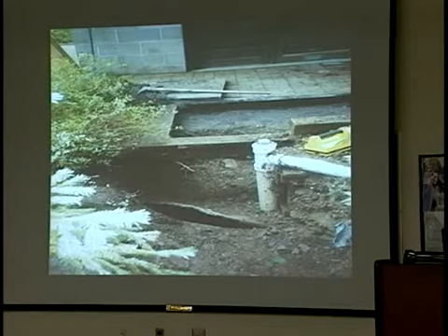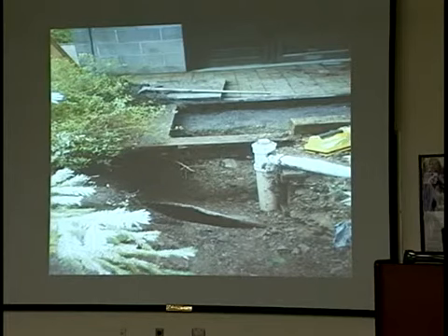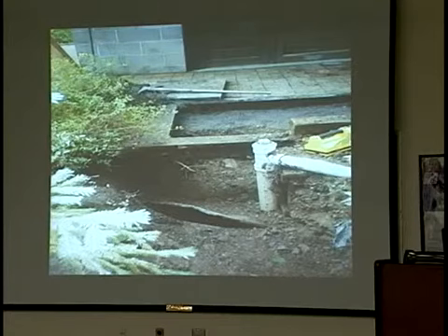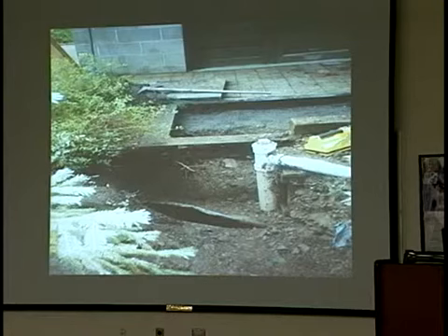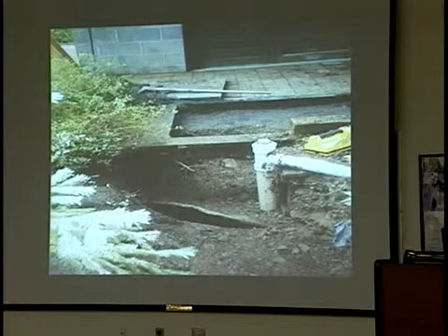Rusted out steel septic tank right on the lake. And this is, I don't know what you people here deal with, but with the weekend warriors. Love these people. They built a guest house up here, put a half a john in there or a half bathroom, ran the pipe down, cut through the top of the steel septic tank. The only bad part about this, it was right over the outlet baffle. A lot of good that was going to do. But when we inspected this system, the tank was empty because it was rusted out, so it was leaching out. So we put a whole new system in again.